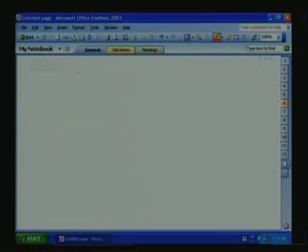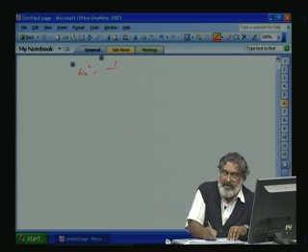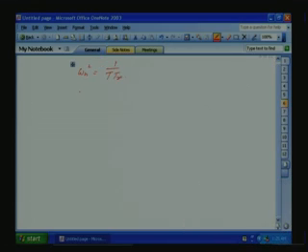So, if you go there, the omega n square equating the previous value will be 1 by T Tr, then 2 theta omega n is equal to 1 by Tr, and theta is equal to root T by 2 root Tr, that is, now theta is equal to 1 by root 2.